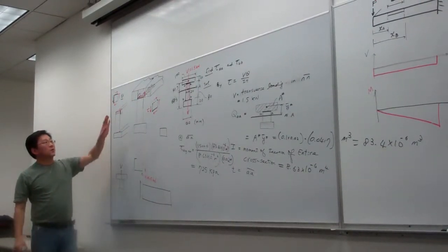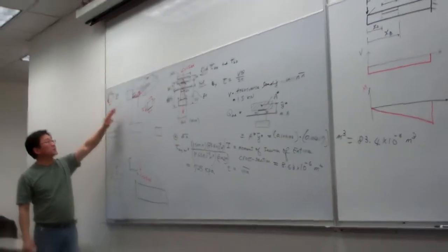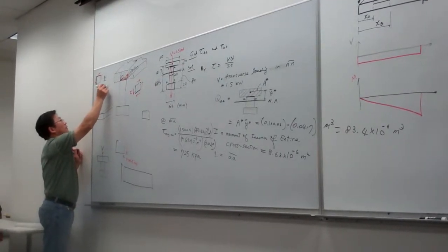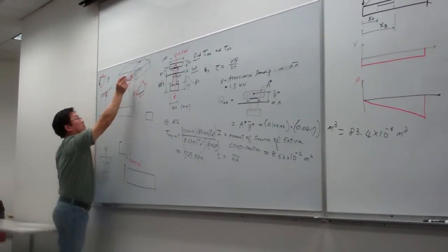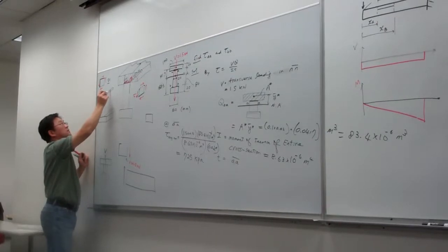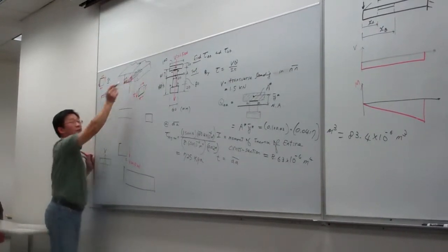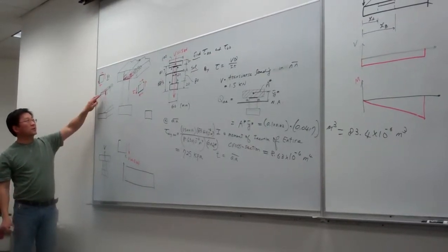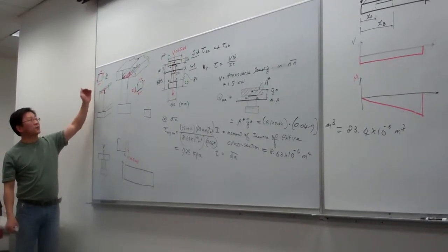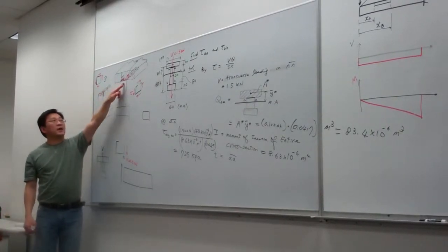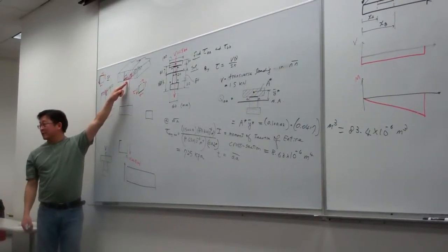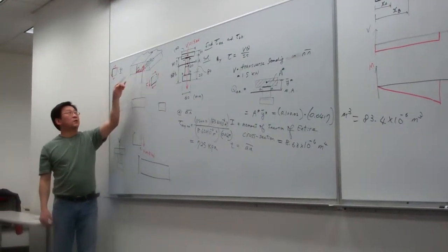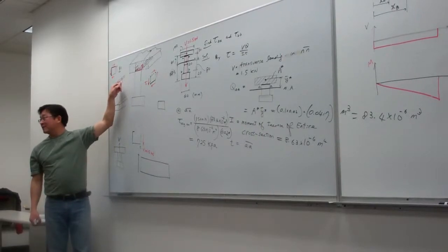Okay. So the conclusion is this. This area, let me call this the interface. This interface is the same as this one. If we pick from this viewpoint, the shear stress on this interface goes in that direction. On the other side, by action and reaction, we have the same magnitude of shear stress, but working in the opposite direction from this viewpoint.